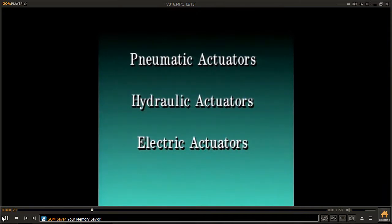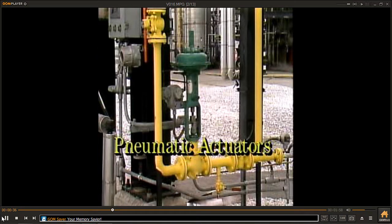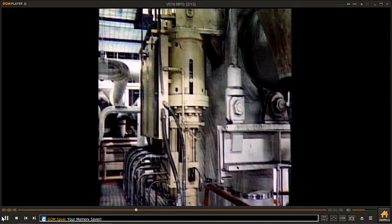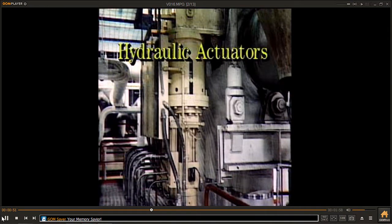There are three basic types of actuators: pneumatic actuators, hydraulic actuators, and electric actuators. Pneumatic actuators use air pressure to produce motion to position a valve. They're probably the most common type of actuator used in process systems. Actuators that are powered by a pressurized liquid, such as hydraulic fluid, are called hydraulic actuators.